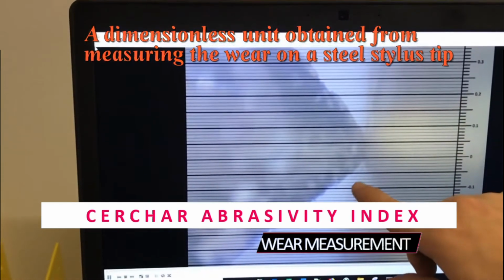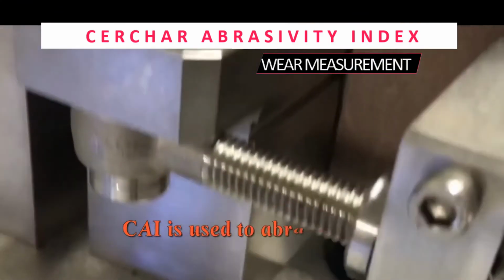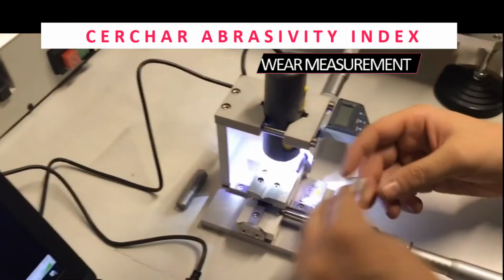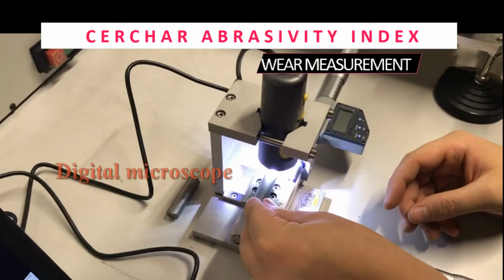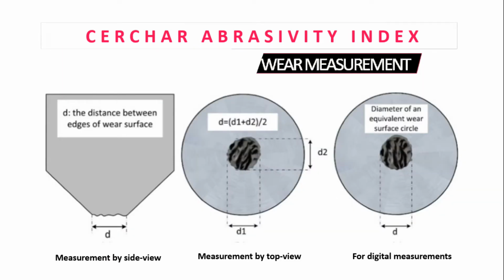The length or diameter of the wear flat D shall be based on the optical and digital methods using a microscope having a minimum magnification of 25 times. The measuring resolution should be at least 0.005 mm with readings reported to the nearest 0.01 mm. Measurements may be executed by side or top view settings. Measurements by side view are however strongly recommended.